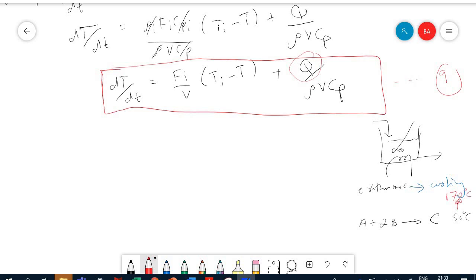And that looks like very exothermic. And because it goes up, the conversion is going to be not as required, and it may go in the opposite direction. To bring it down to the optimum temperature, what we need to do? We need to cool to bring it down to the optimum temperature, where we have the maximum conversion. And why do you want to get the maximum conversion? To sell the product of C. Okay, great. So that is the reason why you're trying to cool if you have an exothermic reaction.